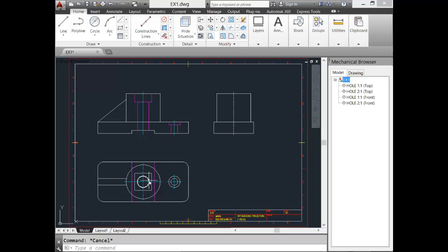The rectangular box from the front view will be the same as in the side view. So I'll go again for my copy tool and copy my box and my hole, and I'll hit enter. I'll pick this base point from the mid of the front to the mid of my side view. This is my projection of the box and the hole. Let's continue. The projection of my counterbore is also a cylinder, and we'll treat it the same way.